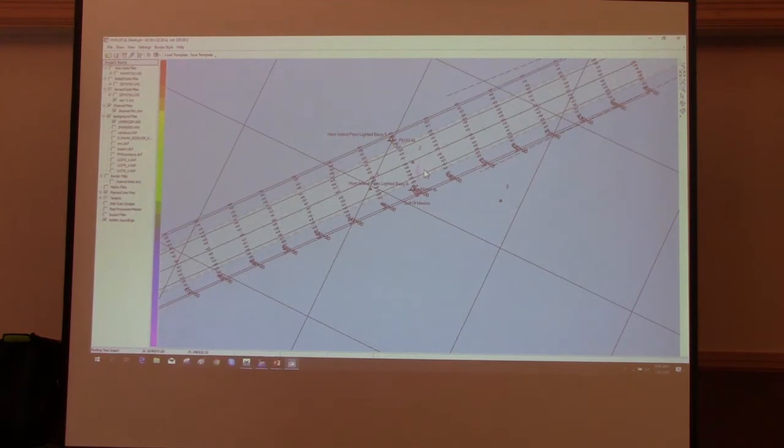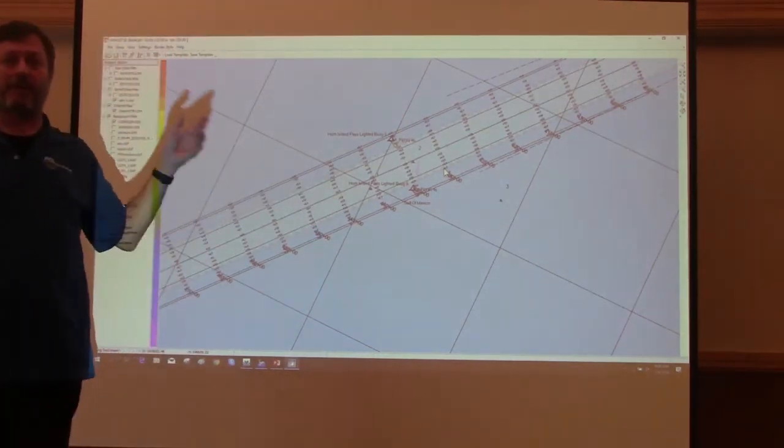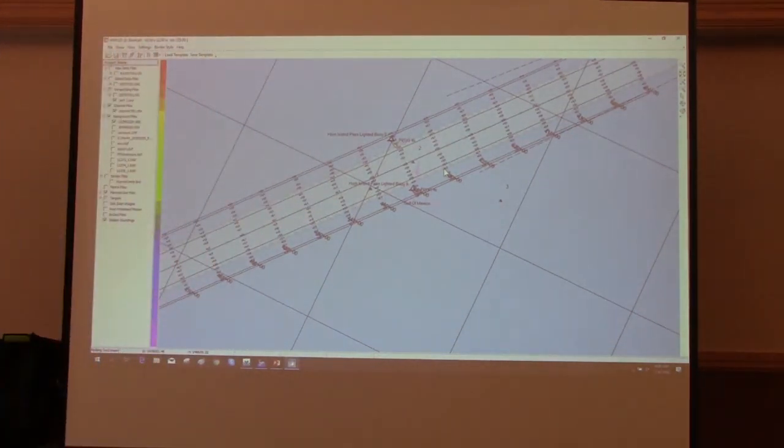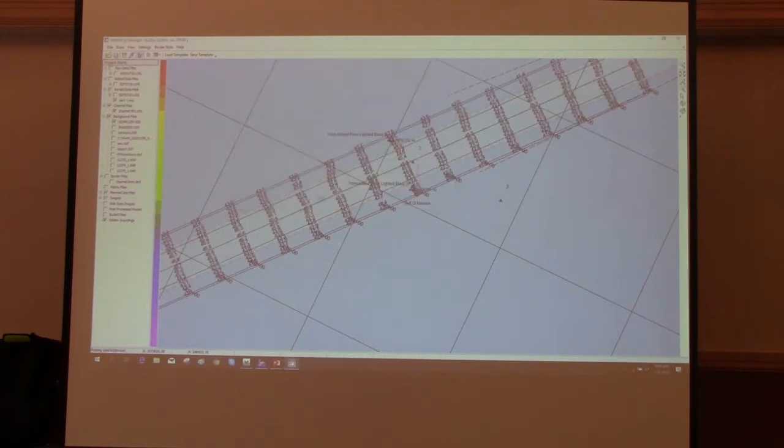But I think one of the best practices is just to use the vector options here. They're going to plot better too, much clearer than the fonts. So that's a nice option here. And if you're seeing the vectors drawing on the screen and there's no overlap, that's the way the vector ones are actually going to print. If I go to the font right now, it's not exactly what you see is what you get, like we say.